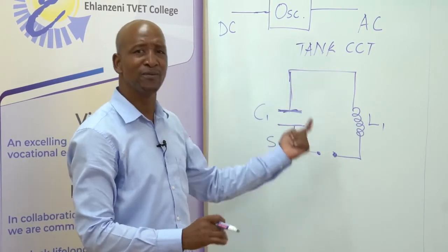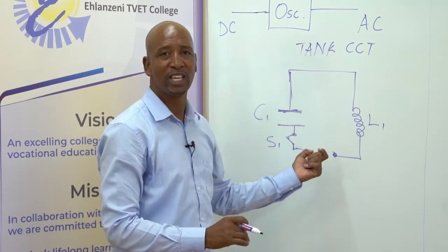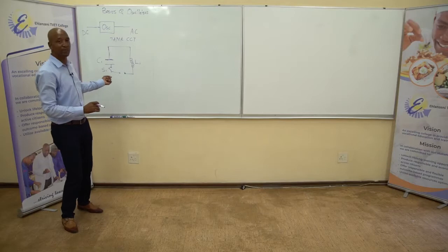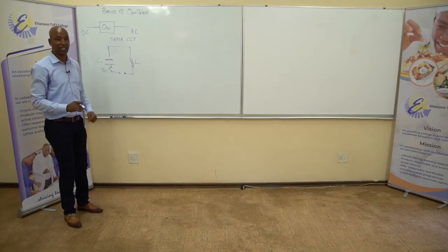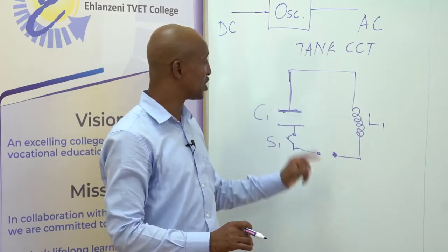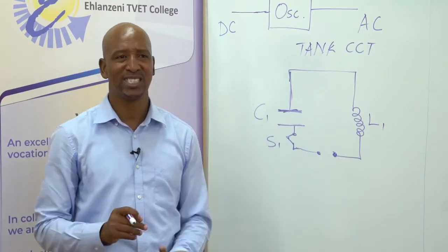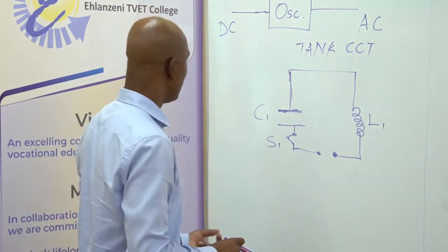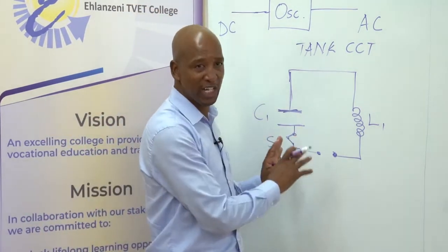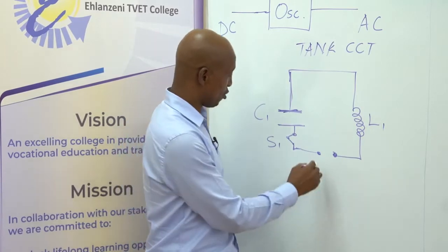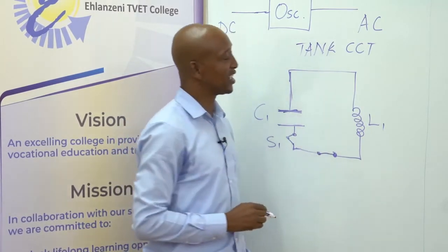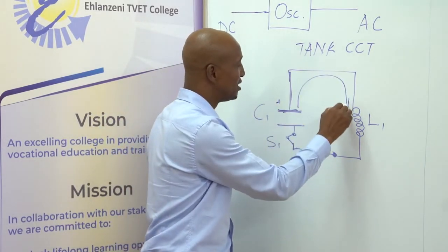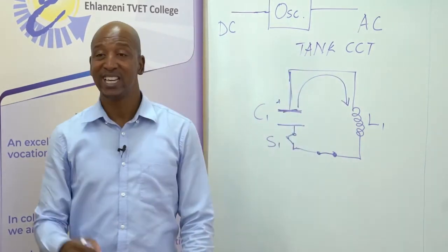That's the main function of a capacitor, storing charge. It can store this charge indefinitely, we say in electronics. We don't know how long it will keep this charge, but we know for a fact that for the capacitor to discharge, it needs to see some kind of resistance, some kind of load across its two terminals. Now, assuming the capacitor is fully charged, we close this circuit like that, and the capacitor will tend to discharge because now it sees a load.